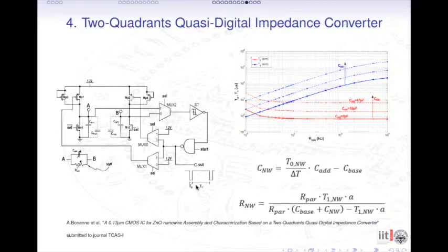And we can also investigate the sensitivity of that nanomaterial to two different phenomena. For example, a nanowire can be sensitive to UV light, with a variation of the resistance, and can be sensitive to temperature variation, which corresponds to a variation of the capacitance of the nanomaterial.